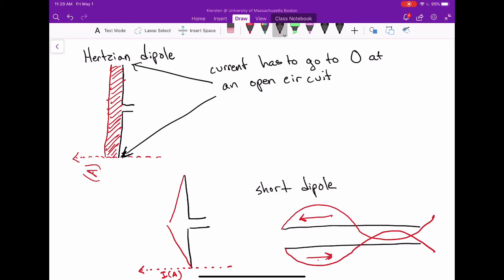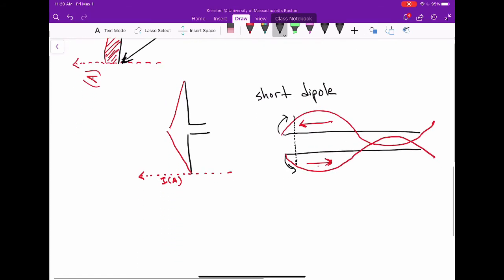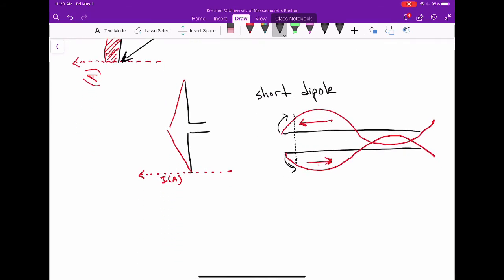Now imagine that you just bent your transmission line here and folded these little open ends out a little bit. The current distribution you got now is that same standing wave on the transmission line with just the very ends of that sinusoid sort of exposed to the air on the outside of the antenna.